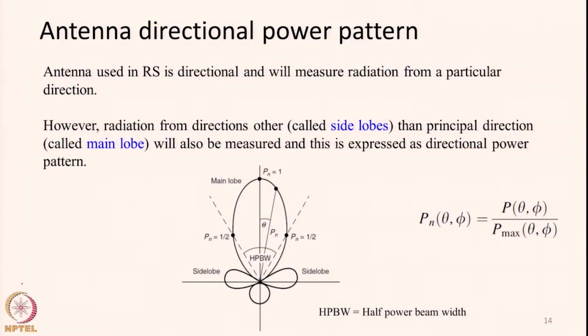So, even though there is one primary direction of energy collection, there will be what is called side lobes, that is, even in different directions a small amount of energy can leak in and enter the antenna. Say a small example is given here. Say this is the primary direction in which the antenna should collect the energy. So, the antenna will collect all the energy up to its maximum capacity coming within this particular direction. So, Pn is nothing but the power collected relative to the power max. Okay. So, this is 1 here, in this is the primary direction.